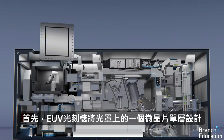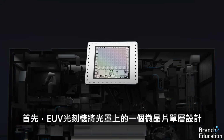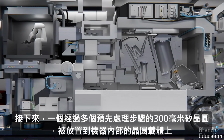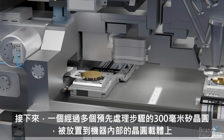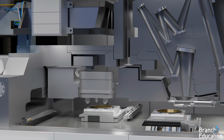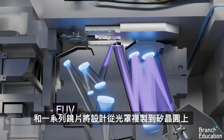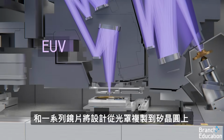To start, the EUV lithography machine takes the design of a single layer of a microchip on what's called a photomask and loads it into the machine. Next, a 300 millimeter silicon wafer with a set of prior processes applied to it is placed onto a wafer carrier inside the machine. With both in place, the machine uses extreme ultraviolet light, or EUV, and a set of mirrors to copy the design from the photomask onto a silicon wafer.